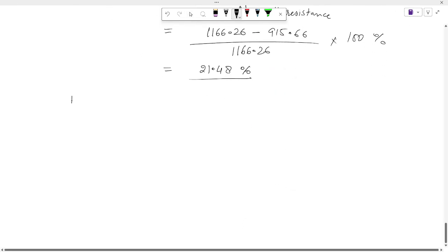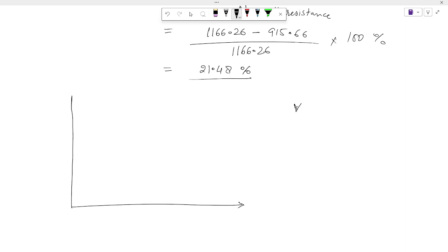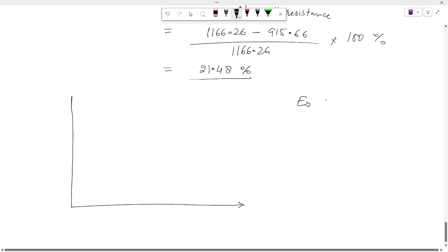And this is a shunt machine, you know. Last time I discussed, it has constant torque? No, not constant torque. Try to understand what I'm explaining. EB is equal to V minus IA RA, yes or no? I will replace flux as constant.